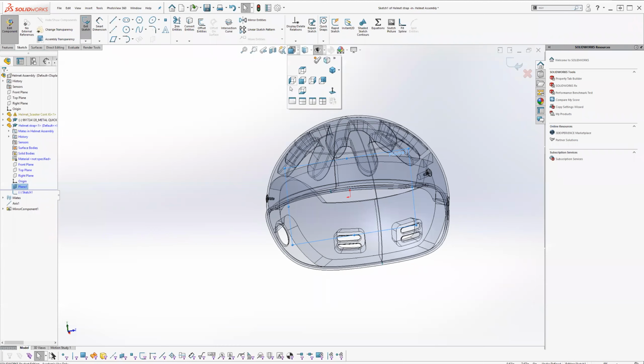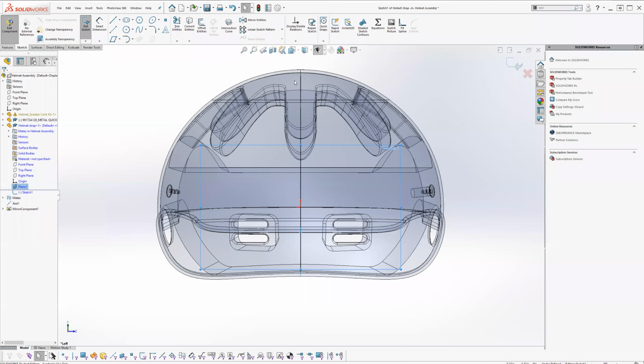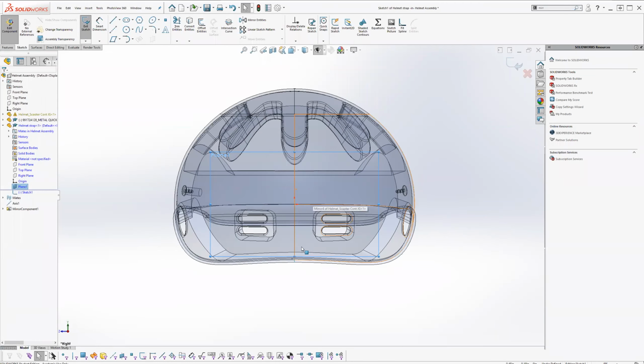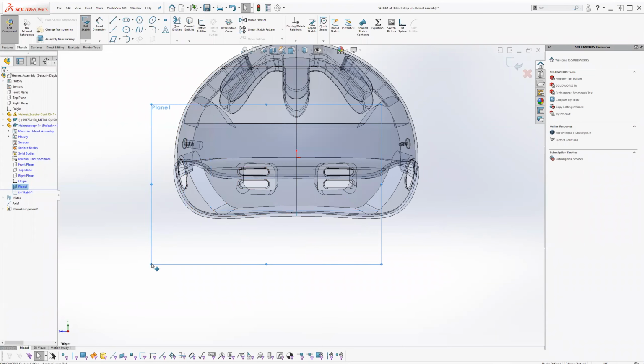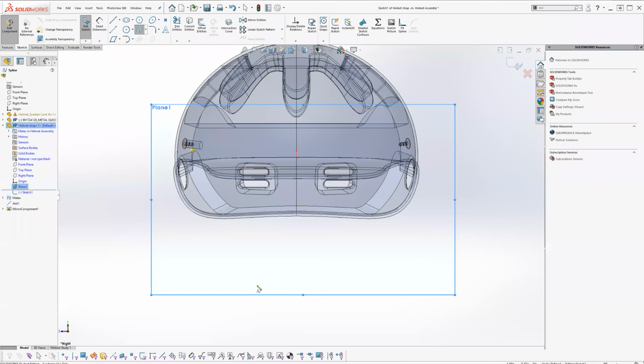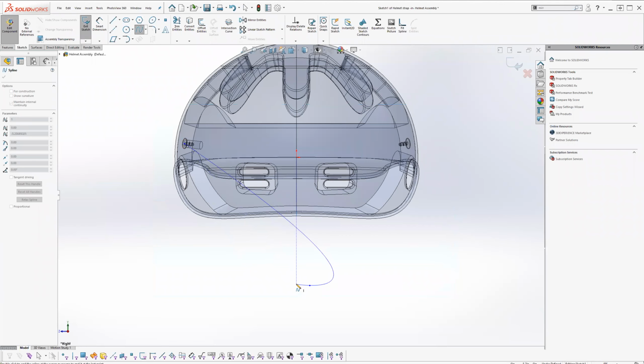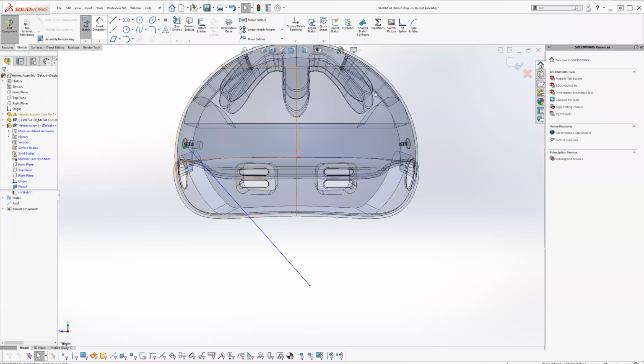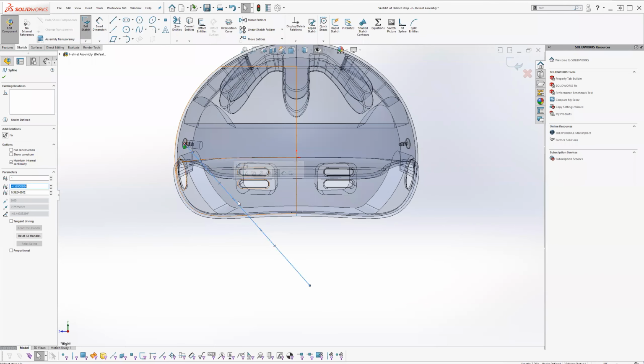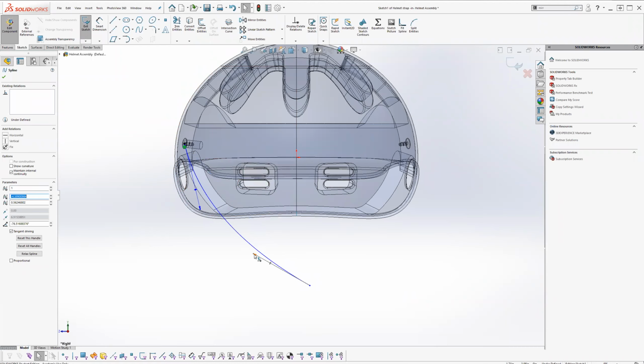There may be two, I'm not sure how you want to create this element. Let's see here. There's my plane, and I'll just make two just so we're kind of familiar with what we're doing here. So I'll start here and maybe end here. So this is a spline. So here are my handles. So let's say that's going to be the strap path.